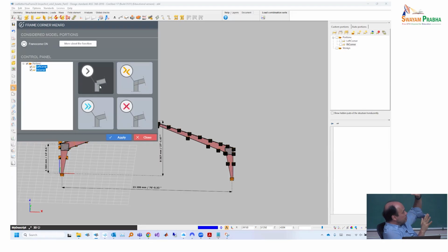So we still do not give any information about how the connection topology is made. The beam element transmits the warping deformation as it would by analogy. And as we saw, in case of a box, this is completely wrong. In case of the diagonal, this is more or less fine. And in case of the combined box and diagonal, it's again completely wrong.